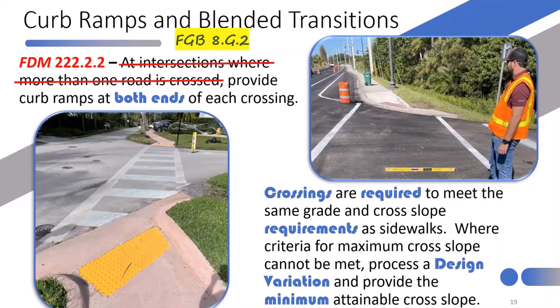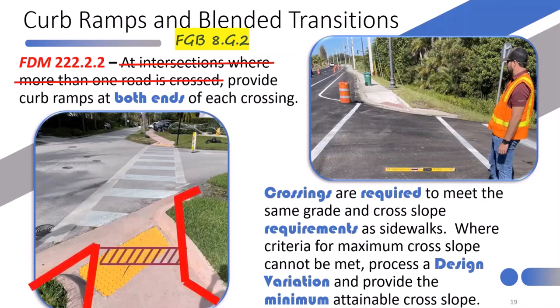So in other words, you can't have a curb ramp on one curbed end of the crossing and then lead them across the roadway to a corner that is missing the curb ramp, because they'll be stuck in the vehicular way. So we need to give our pedestrians a way in and a way out, and that speaks specifically to both safety and accessibility.